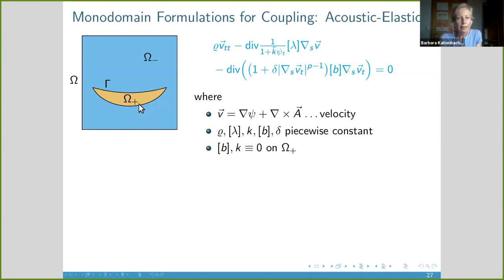Inside the lens domain, inside the solid domain, in this Helmholtz decomposition that we make use of here, both components are present. Outside in the fluid domain, recalling that the velocity is irrotational there, we only have this gradient part of the velocity.